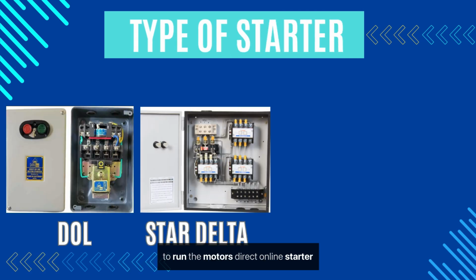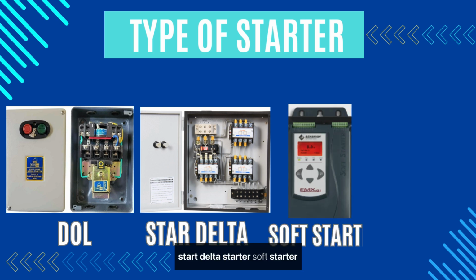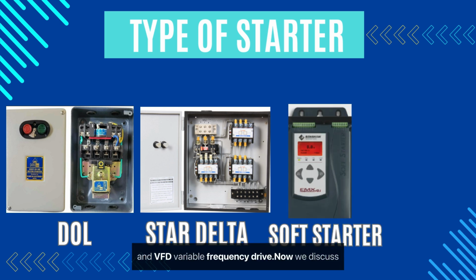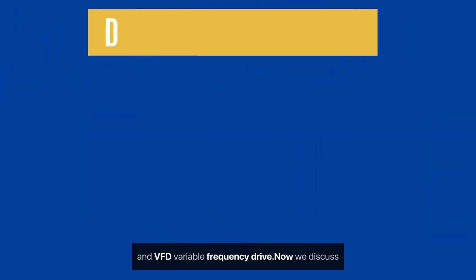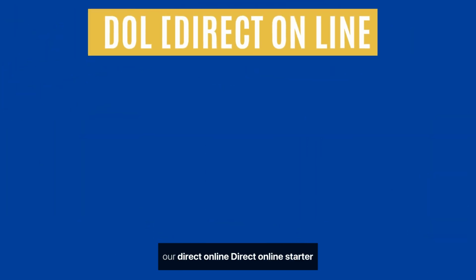Direct online starter, star delta starter, soft starter and VFD, variable frequency drive. Now we discuss the direct online starter. A direct online starter is a type of electrical starter used to start an electric motor. It is one of the simplest and most common methods for starting an induction motor.